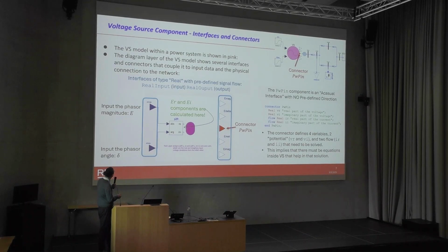Okay, so that's the voltage source, but of course, if I'm going to build this grid-forming converter model, then I need to control it to mimic the two control functionalities that they asked me for. So basically, the basic building block is to make a controllable voltage source, which will have as outputs the internal voltages, because remember there is an impedance inside of it, both in, what's it called? Polar and rectangular coordinates. And here you have inputs that are going to be provided by the controllers in terms of magnitude and angle, because this is very typical the way that we model things in power systems.